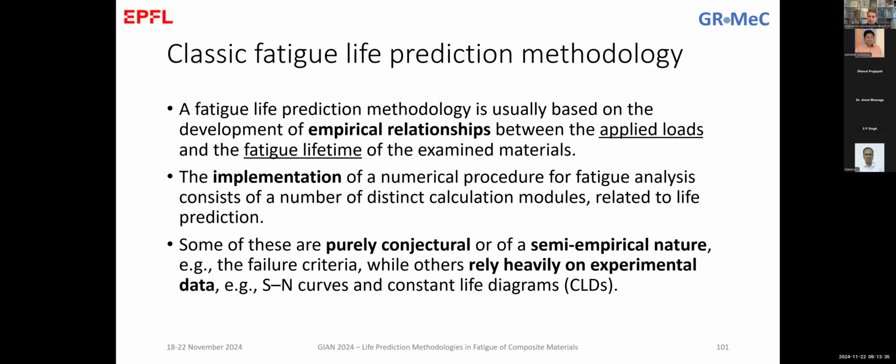The simplest way is either with the stiffness based failure criteria that we introduced in the previous slides, or by using the phenomenological failure criteria that we introduced now for stresses or strains, and the damage rule that is based on simple Miner calculations.